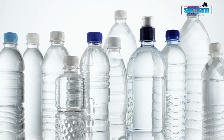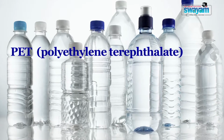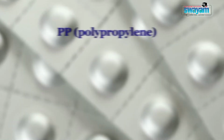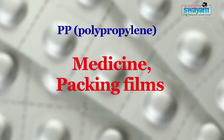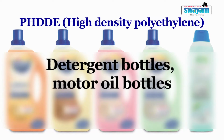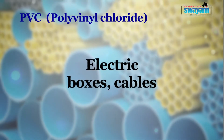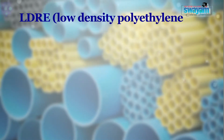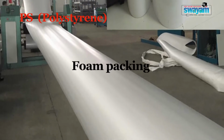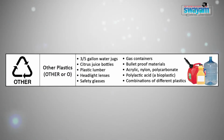Now, how can plastics be classified? Plastics can be classified on the basis of the chemicals involved in manufacturing. First is PET, polyethylene terephthalate; soft drink bottles are an example. Next, PP, polypropylene; its examples are medicine packing and films. Third is HDPE, high density polyethylene; its examples are detergent bottles and motor oil bottles. Fourth is PVC, polyvinyl chloride; its examples are electrical boxes, cables, etc. Next is LDPE, low density polyethylene; its examples are tubing and plastic bags. Next is PS, polystyrene; its examples are foam packing and others. The other plastics are thermoset plastics, nylon, etc. They are examples of other plastics.